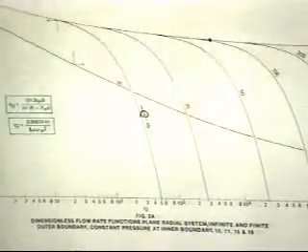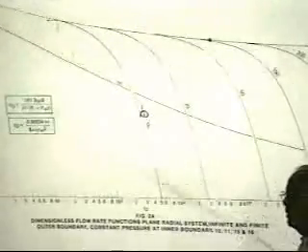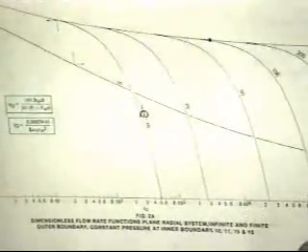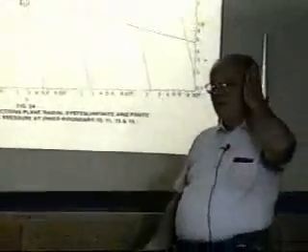Something you really have to recognize here is the concept of using effective wellbore radius, you know, the skin, with a stimulation. Frac'd wells, I think you can get an rw prime of about 50 feet, Mike, would you say?